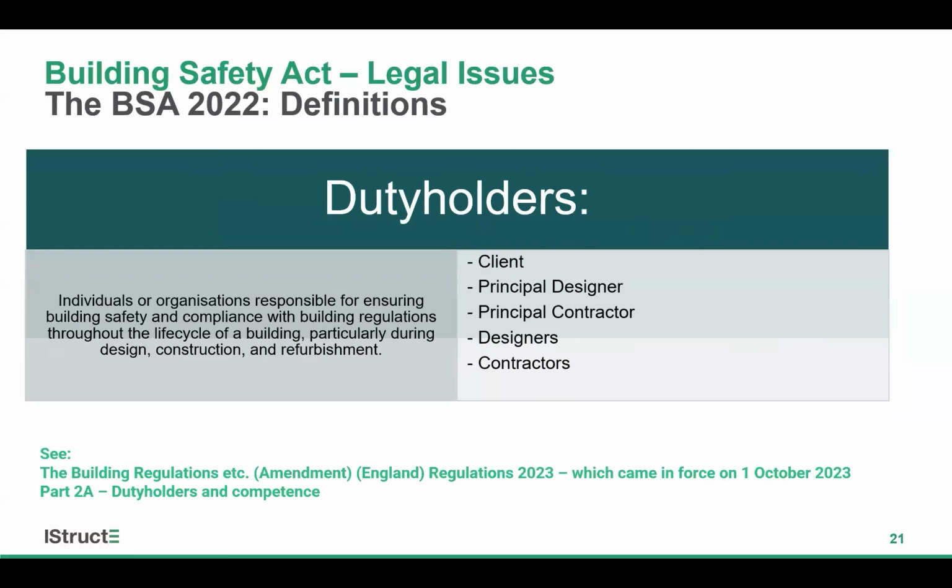The duty holders then, so they are the client, the principal designer, the principal contractor, designer and contractors. And the BSA has introduced the duty holder regime, which sets out these new roles which need to be filled when carrying out new construction work and work to existing buildings. So the new duty holder regime doesn't apply just to higher risk buildings, but to all projects.